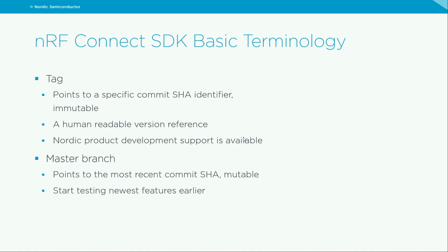For the tag, Nordic product development support is available, so we would like every developer to use a tagged version of the nRF Connect SDK. It has been tested more with CI testing, etc. But if there is a feature that you do not see in the latest tagged version, but you find it in the master branch, you are able to check out the master branch and start testing the newest features earlier than having to wait for the next tag of nRF Connect SDK.